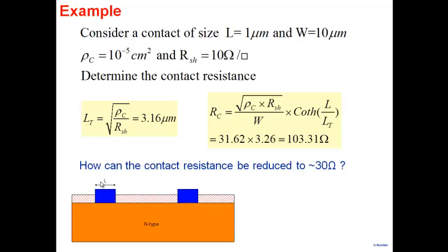As a designer, you can prescribe that. So you can tell, make a contact which is 10 micron, which is fine. So it will reduce it to this value here. Length, obviously, in this case also the area increases. Overall device area, you can imagine that 10 micron you're using here, 10 micron you're using here. So overall, this thing increases here.